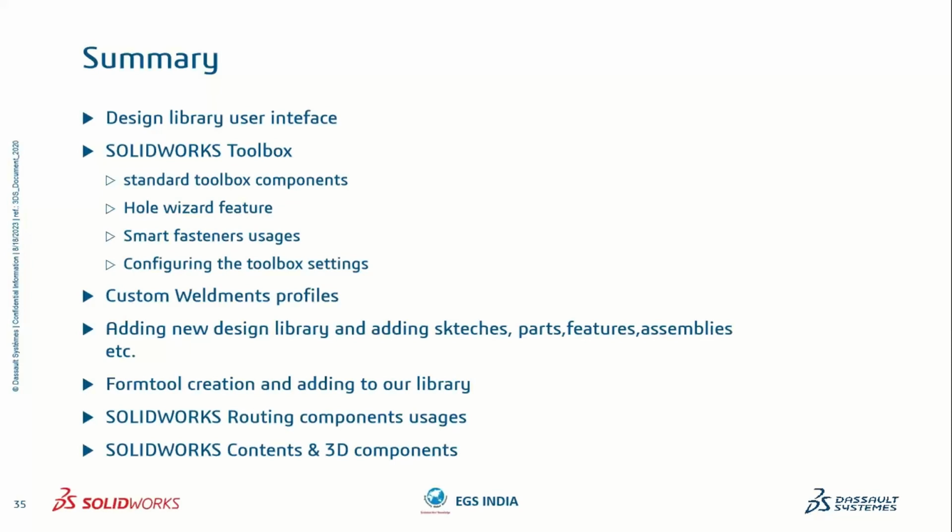Also the SolidWorks routing components can be used and managed in our routing library manager. And then the SolidWorks content and the 3D components: by using our cloud libraries we can download those components, map them, and use them in our models. By following these steps we can work faster, save time, and release our drawings faster